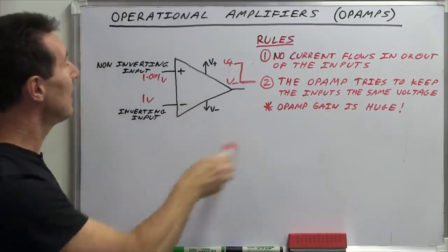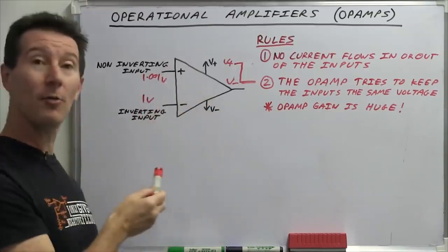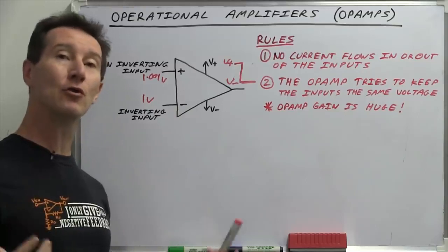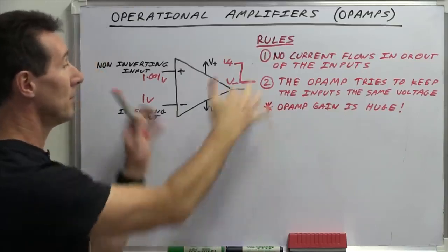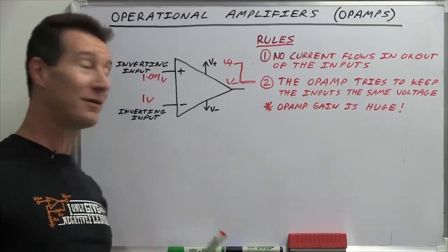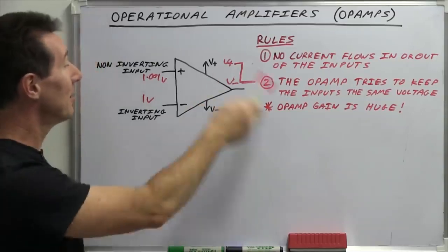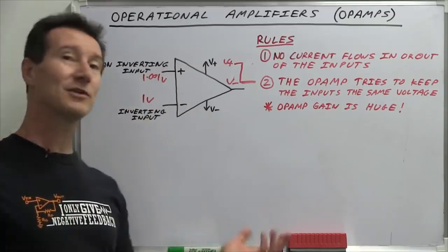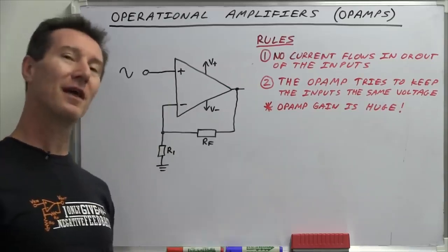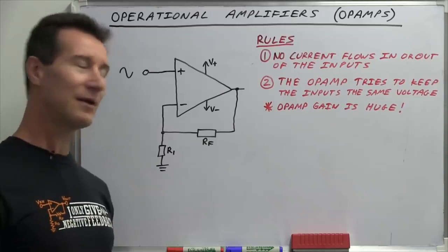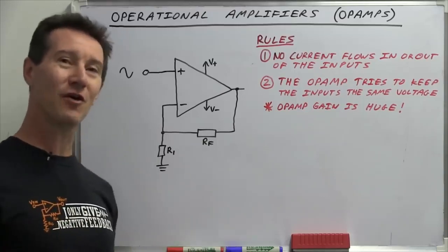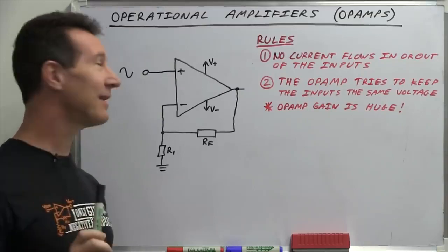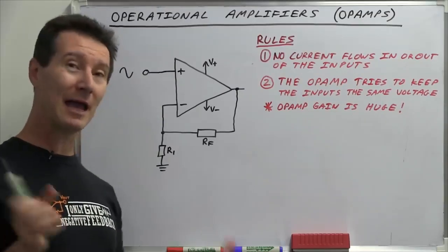But that's what happens if you connect an op-amp with no feedback at all, and what that's called is the open loop configuration, because there is no loop. The loop is open, and we'll close the loop in a minute, but with an open loop configuration like that, an op-amp is just a comparator. So now that we've got that little non sequitur out of the way, the oddball configuration of the comparator for the op-amp, let's have a look at where op-amps come really useful, and that's as proper amplifiers.